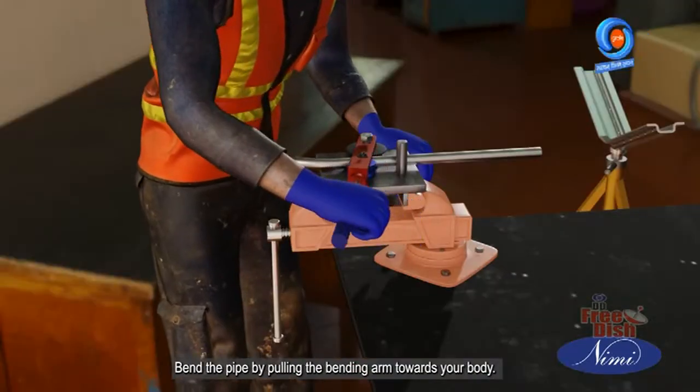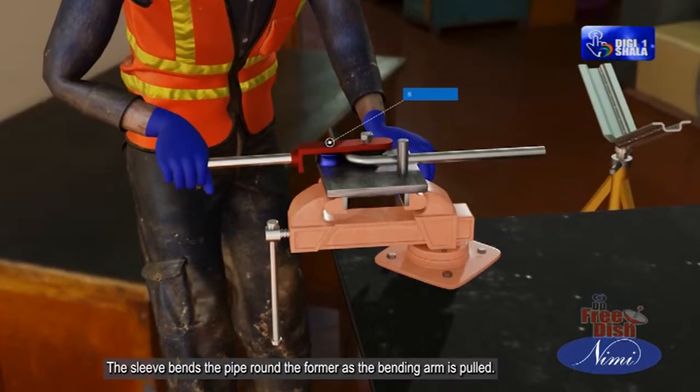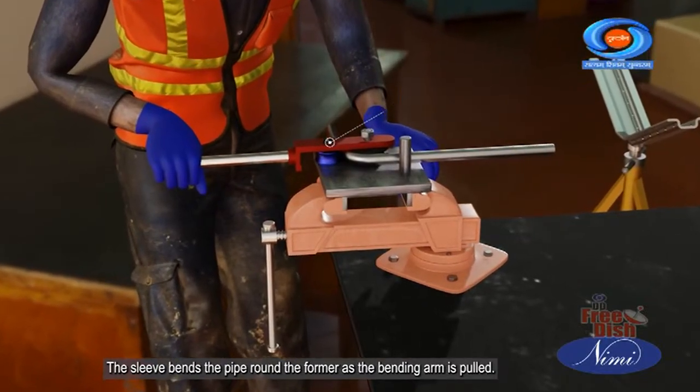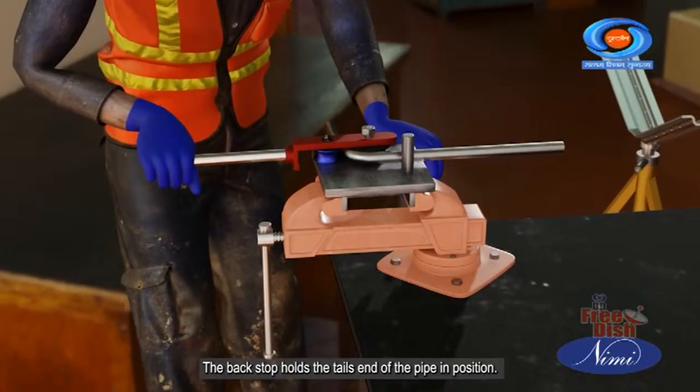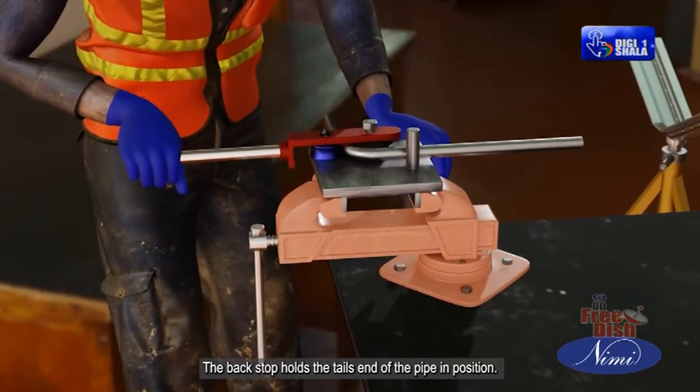Bend the pipe by pulling the bending arm towards your body. The sleeve bends the pipe round the former as the bending arm is pulled. The backstop holds the tail end of the pipe in position.